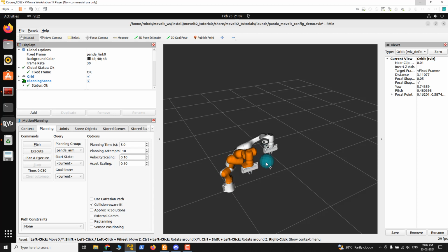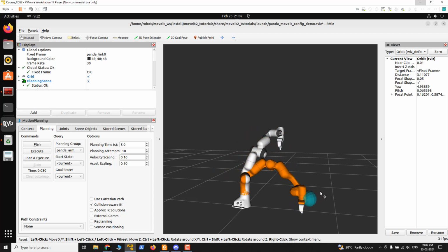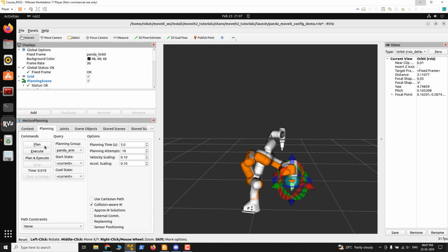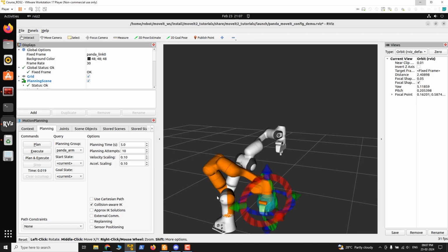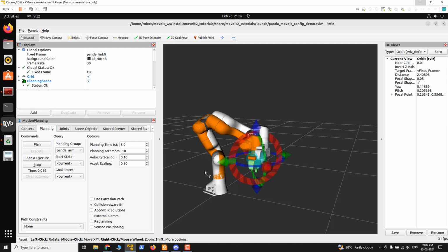Suppose I just want to experience this inverse kinematics. If I give that XYZ, then the trajectory will automatically execute according to MoveIt, as you show. Then finally it will reach the goal position. Then it will have many joint angles, say theta 1, theta 2, etc. So can I see that, or can I get it as an output of some service or some joint message or topic? Yeah, final joint angles, you will get it.